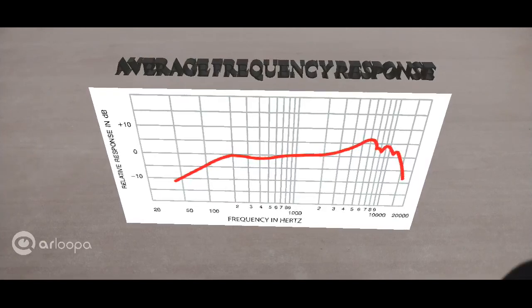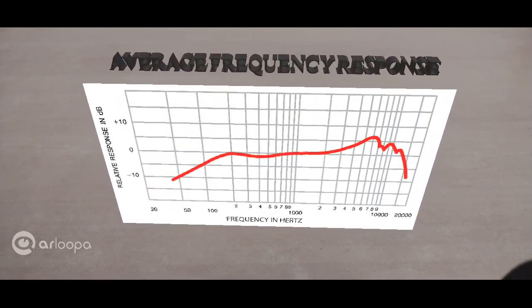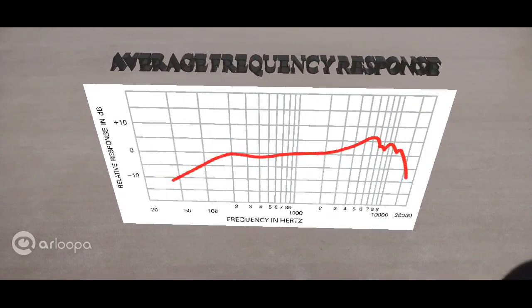That's right, because here, as you can observe, the frequency response is flat from 200 to approximately 2500 hertz, and that's good enough because the human voice is going to be in that range, and you're not going to be using treble or bass in a telephone. So there is no need to have a flat frequency response in the bass or the treble region, because the purpose is solved if you have a flat frequency response in the mid region, and you can have good speech intelligibility in that region.